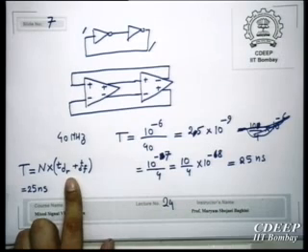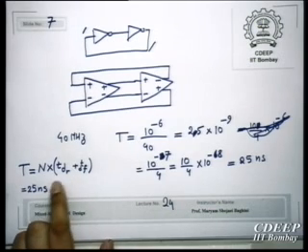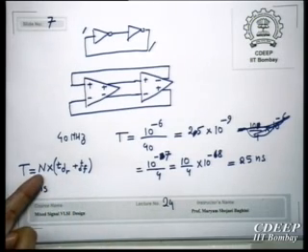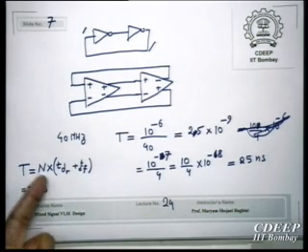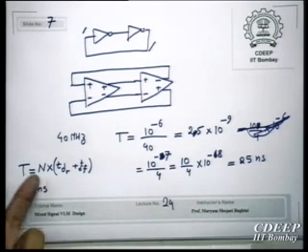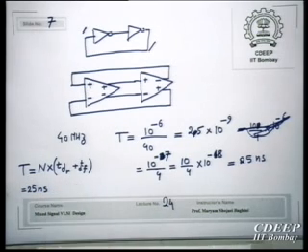You will adjust it. But then suppose, for example, if you use 21 stages, then say 25 stages, it means that this will be around 1 nanosecond. So 1 nanosecond, to make a delay element with a value of 1 nanosecond.